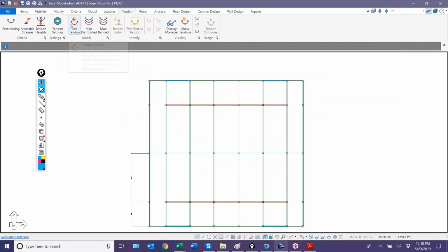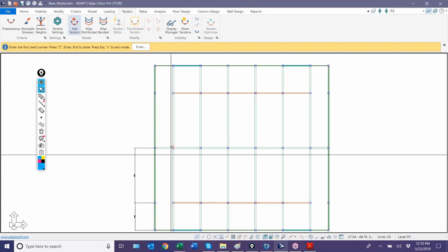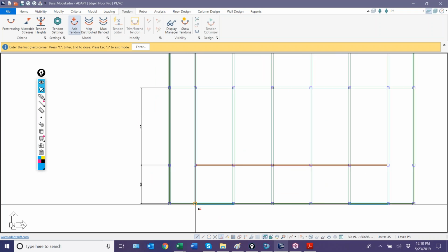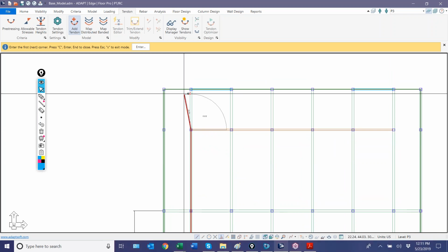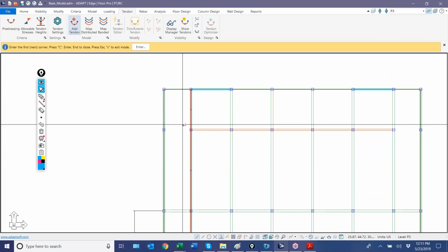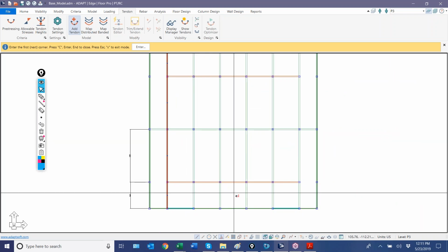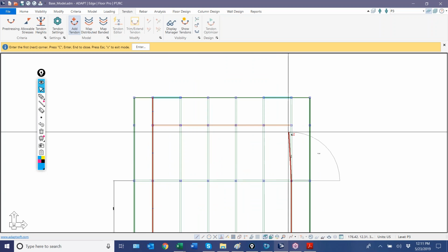So once that's set up, I'm going to add a tendon and then I'll replicate it. For this first line, this is going to be a continuous tendon through. I'll start at the bottom and I'm just going to snap on my column locations. These are basically the high points, and then the 2 end points are the CG. Those are the anchors for the tendon. These tendons here are a little bit different, so I'll just skip over to this one. This becomes the same thing.